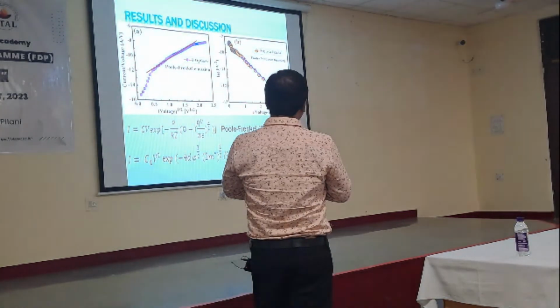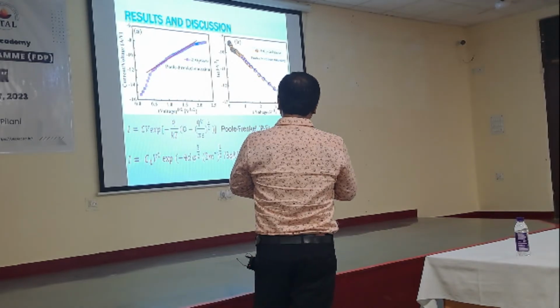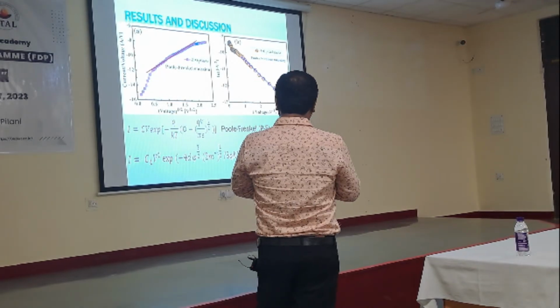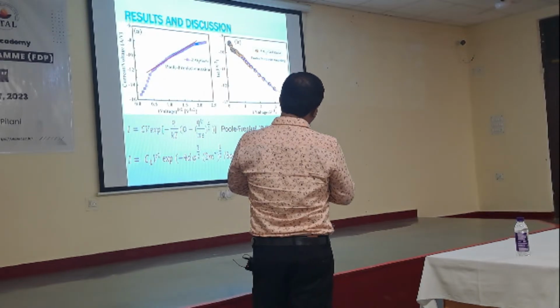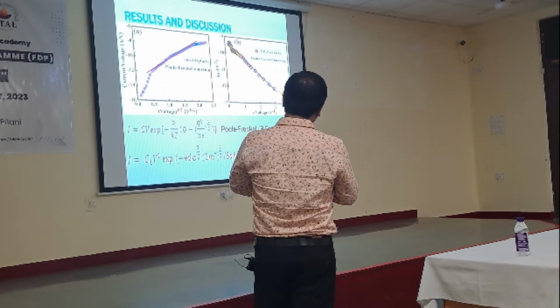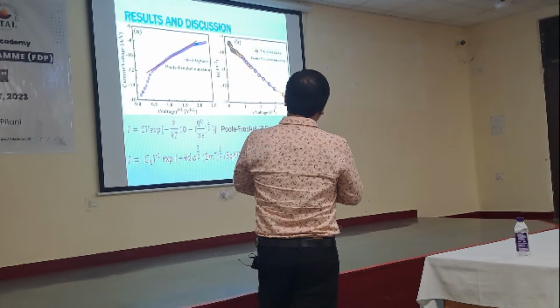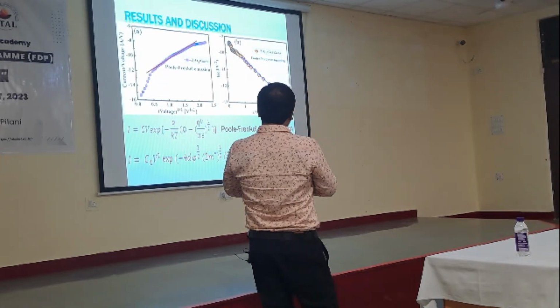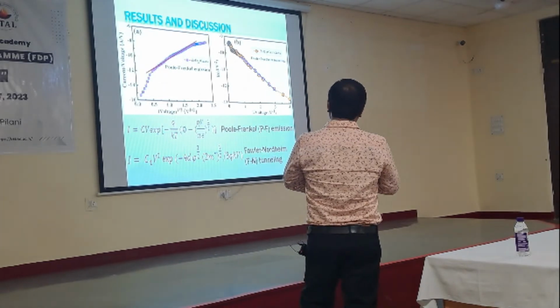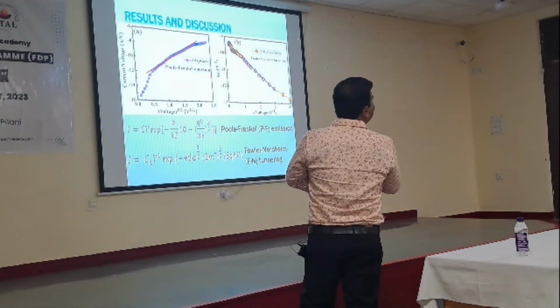In the case of the passivated devices, if you plot them according to the Fowler-Nordheim equation, you get this type of characteristic, which is also linear. From 1 to 4 volts, you can confirm that your device followed Fowler-Nordheim tunneling, because in this voltage region the current followed the Fowler-Nordheim equation.